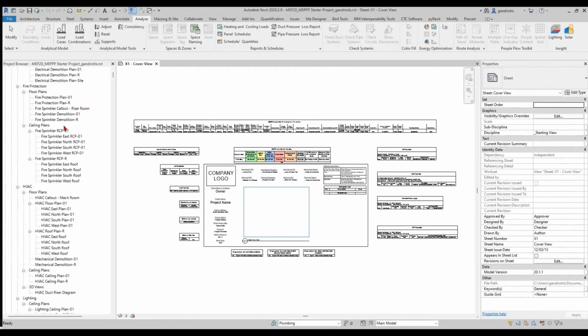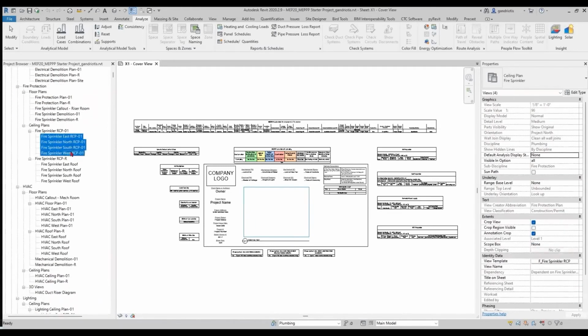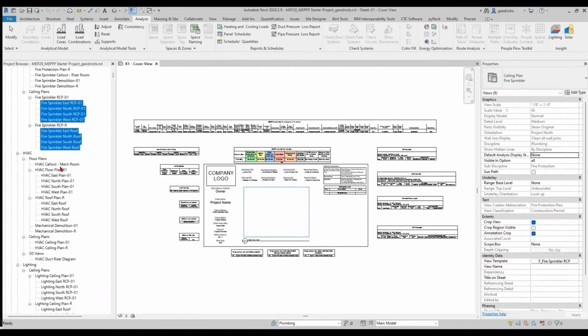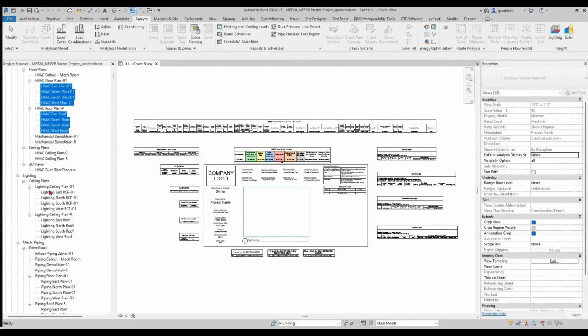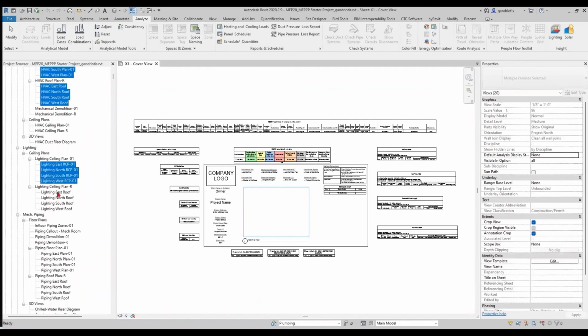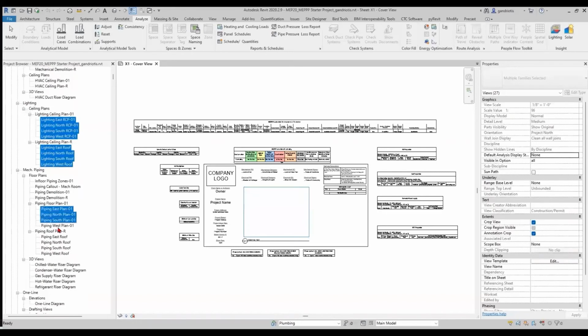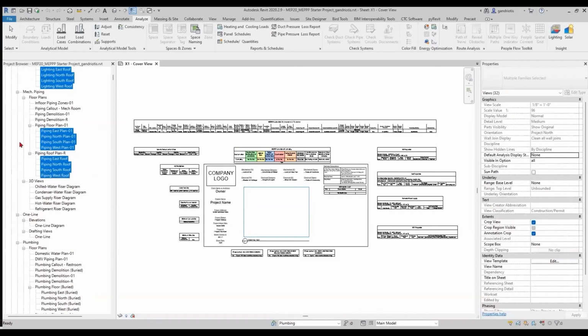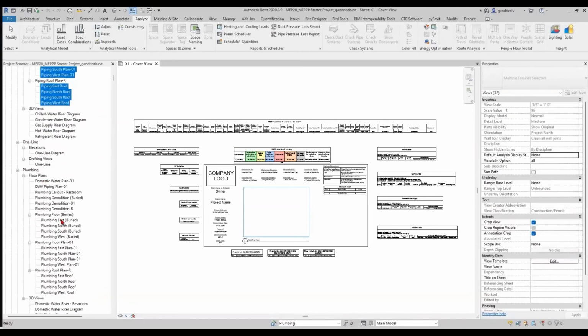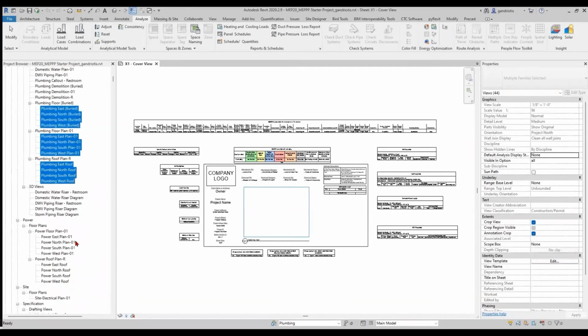So I just did an expand all there just to see if I could find these east, north, south, because all of those have to go as well, like I said earlier, just to slim this down as tightly as possible. And then once I'm done inside of the construction set, I'll go down to the model setup and do the same thing. Just make sure there's no north souths.